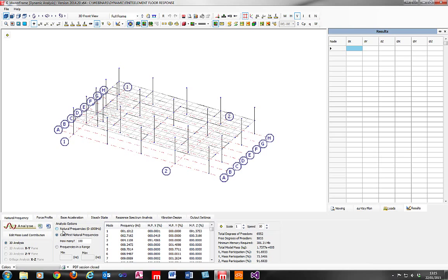For small structures or non-finite element structures, it is often absolutely fine to say that you want to calculate practically all natural frequencies in the range of 0 to 1000 Hertz. Now when you are using finite element analysis, I would highly recommend that you don't calculate all the natural frequencies, because that has an adverse effect on the analysis time, but also an adverse effect on the amount of memory that's required. So it would typically not be necessary to calculate all natural frequencies in a structure. But the question is, how many do you calculate?